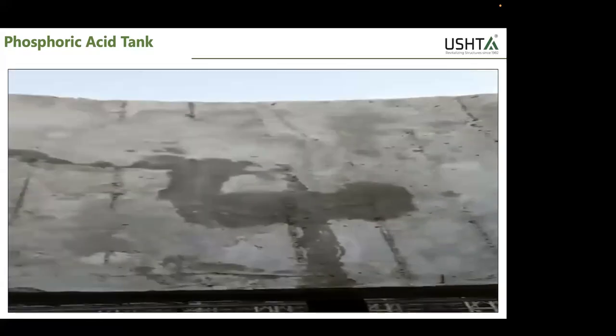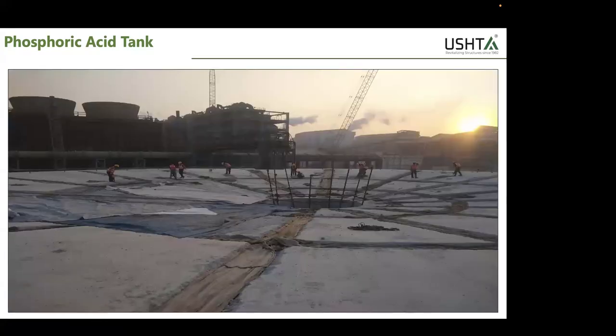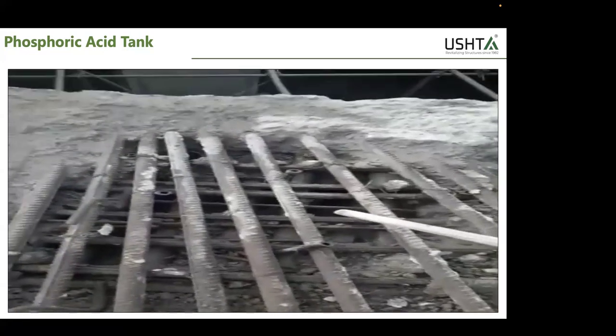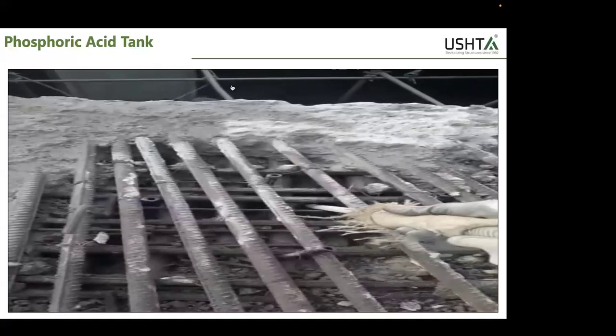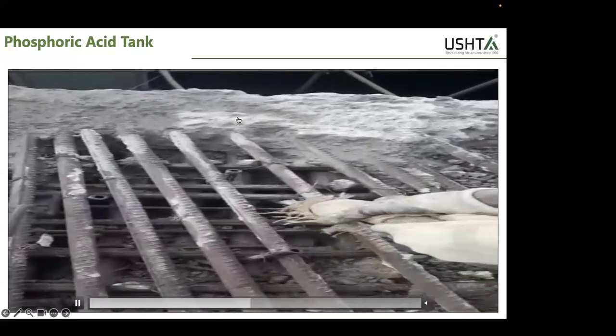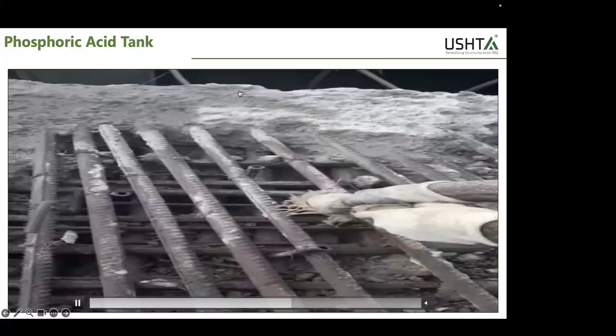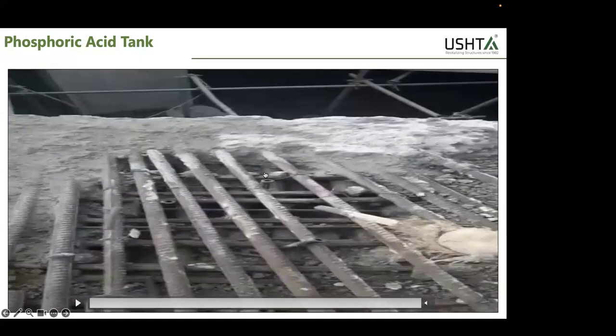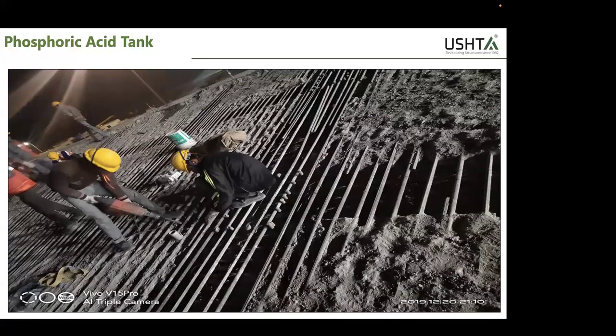So then we started opening up the patches, and we realized that there are huge voids. You can see, because of dense reinforcement, the concrete was up ahead here. The 50 mm cover became 130, 160, 200 mm above. The concrete did not go inside. You can see there are voids. We started opening up, and you can see all this was hollow. And imagine 10,000 tons of material weight was going to come on here.